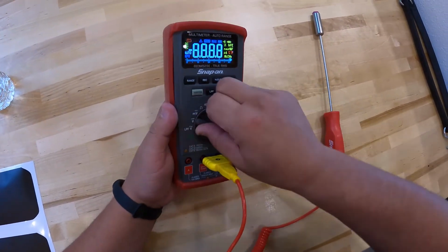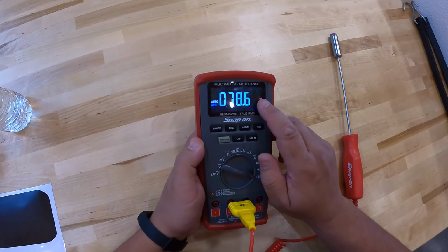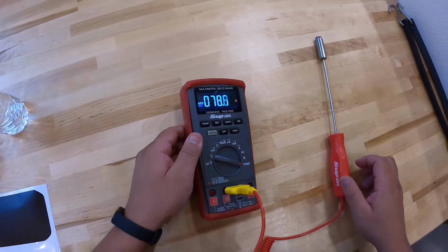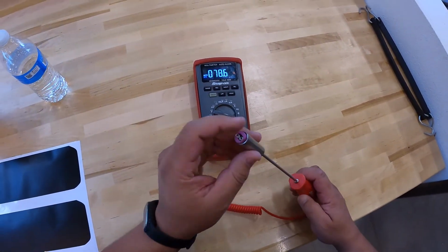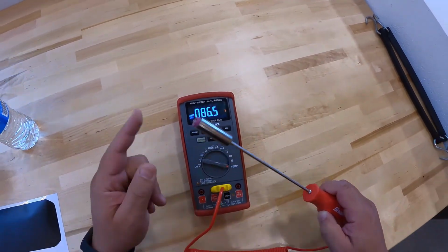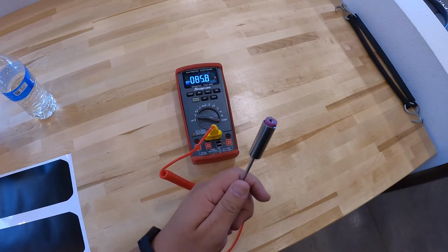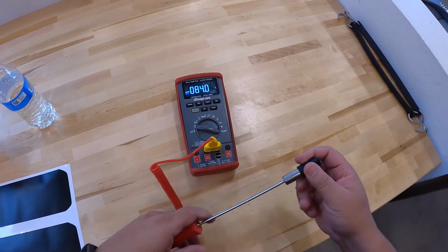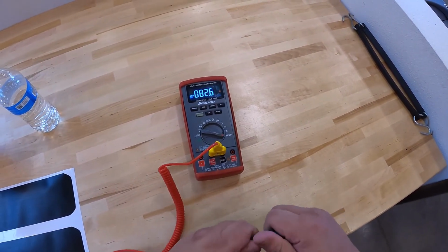From there, you're just going to spin your DVOM to temp, and it should read in Fahrenheit, so about 78.6 for me. The temperature probe has 2 springs on it. Whenever you want to measure the temperature, touch it to something. It's a contact probe. If yours has this little cap on the end of it, make sure you remove that cap first to get a proper reading.